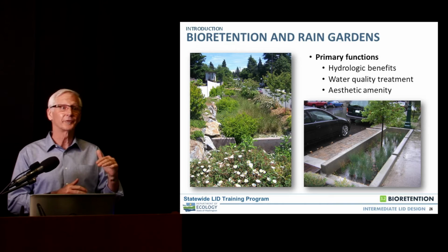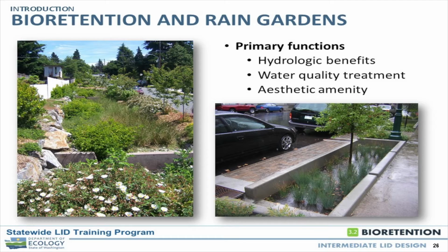And there are now guidelines, right? There's a memo from the Department of Ecology about restrictions of where you can use the current bioretention media in proximity to sensitive receiving waters. But that 60-40 mix might be fine. It might work beautifully depending on your setting, if you're infiltrating to an adequate subgrade. Then again, it might not be. And if you have an underdrain to a receiving water, you have to think very carefully right now about what media you're using, how you're applying it.